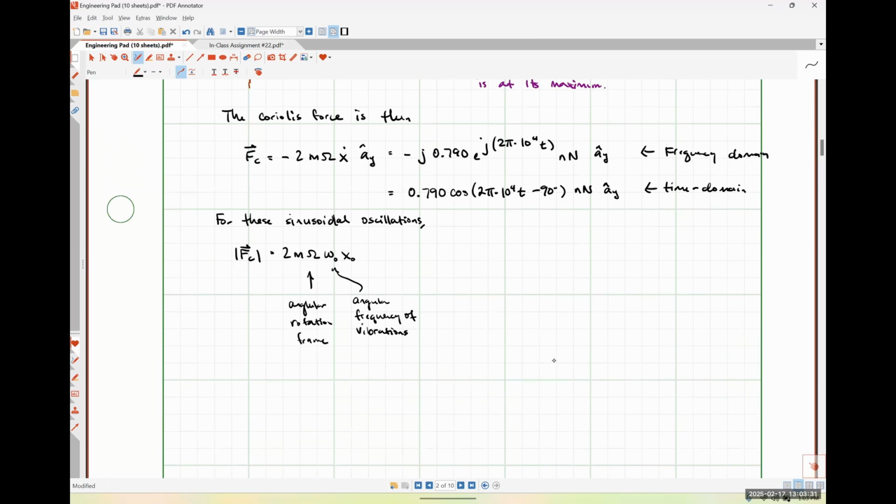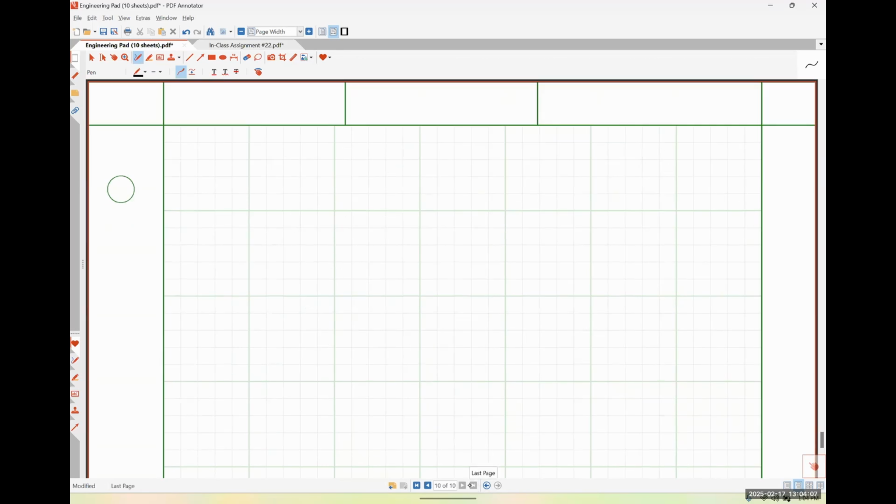The fact that I'm multiplying by negative j is why I'm subtracting 90 degrees from that phase angle. Yeah, so that took care of the negative sign for me. If I put it in the time domain like this, I don't want to get too far into the weeds of electrical circuit theory or anything like that. So this is a quick aside, and for those of you that have had me for circuits 1 or 2, take a nap for 3 minutes.